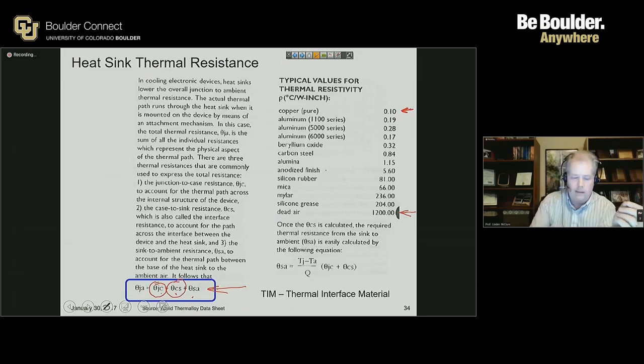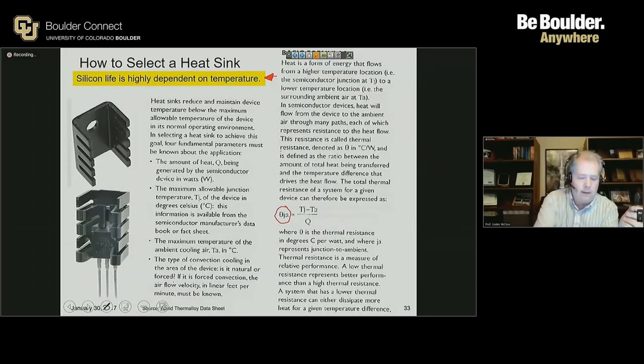If you look at the heatsink, you can see that it's physically attached to your package. And in this case, it looks like it's just attached through pressure. So because of how the spring clips are designed on the heatsink, it's providing some pressure to the surface of the regulator and allowing us to get heat out of the package.